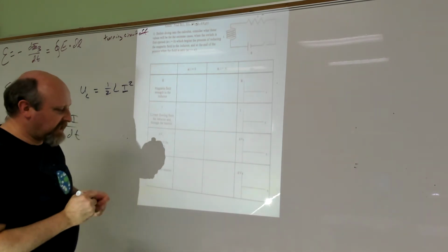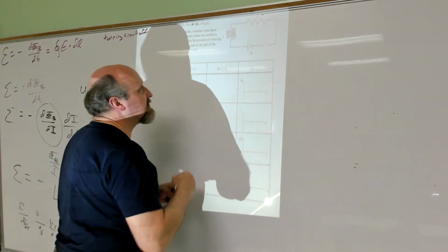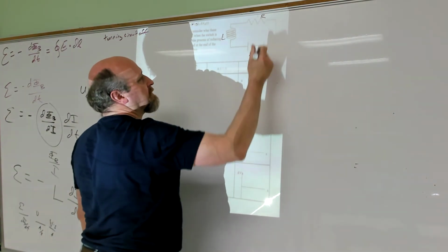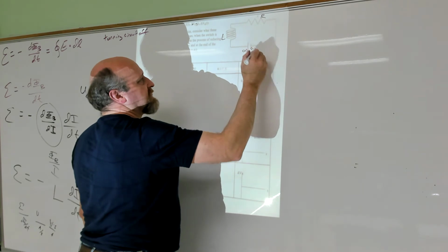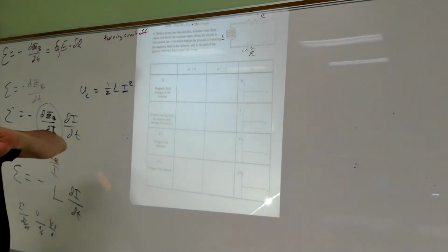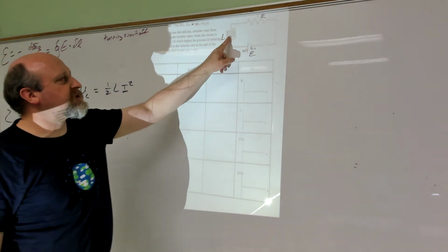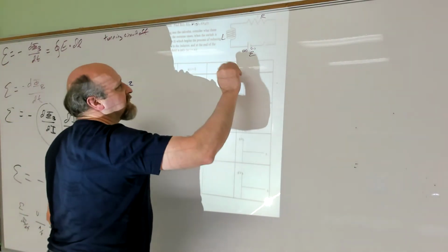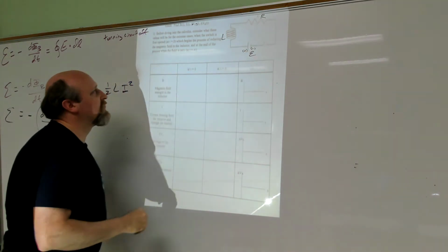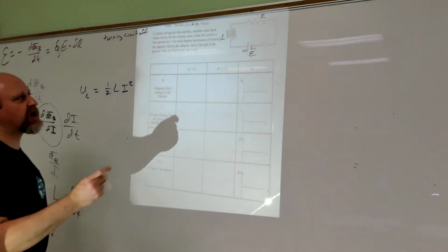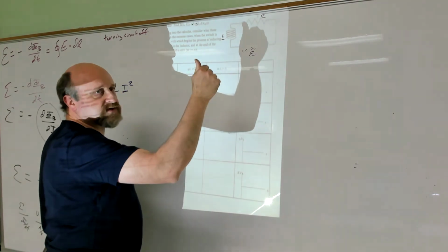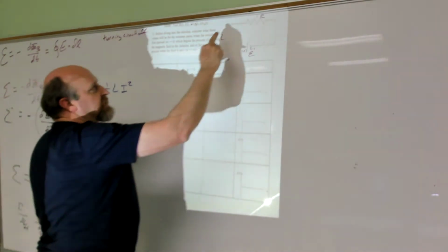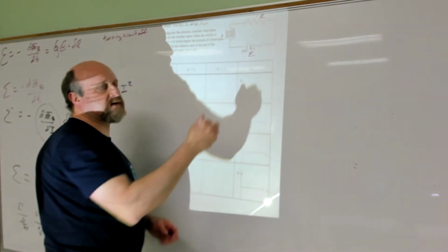We already know there's a lot of energy stored up in the magnetic field in that inductor. It's the high V side and the low V side. Some energy is stored up here, so when I flip the switch, energy starts getting drained out of here to push the current and keep the current flowing, to fight against the change, to maintain that magnetic flux, to keep the current flowing through. So at the very start, at time 0, I open the switch, turn the circuit off. Now, this thing is going to act to try to keep the current flowing.